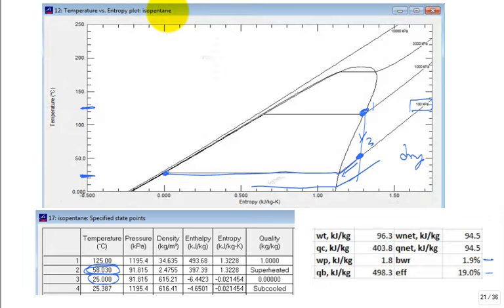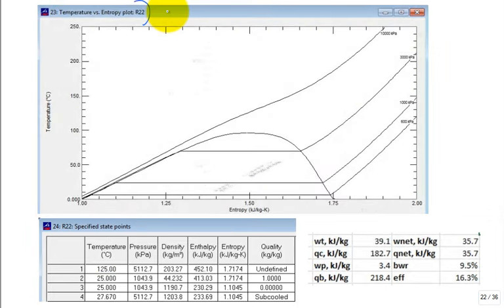Check another fluid, R22. This is a working fluid that's in a lot of residential air conditioning systems. It's been phased out gradually, but it's probably still in a lot of homes. And look at the shape of that dome. Symmetrical. True? And if you're coming in, though, at 125, guess what? You're above the critical point. So maybe I've got to figure out where I'm going to stop it. I don't know where I'm going to stop it.